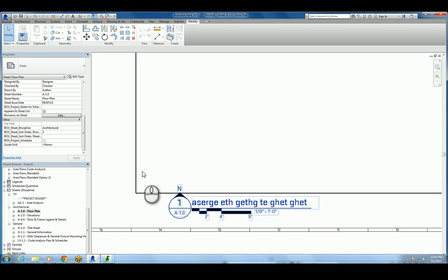Also, we get jokers that will print it from PDF and do their takeoffs. And this has happened. They order the material and say they're short on material. I don't get what happened. You printed it using print to fit to whatever printer you had, it didn't scale, and you used an 1/8 inch scale, and the drawing wasn't 1/8 inch. So that's happened before too. Not just us, to everybody around the world. You just get guys doing it. So it's kind of a fail safe, just to say, hey, we had a scale on there. You should check the scale.